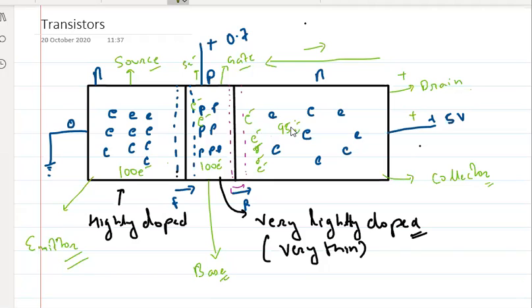And if this process happens rapidly, without any constraint, it will produce very high heat, and this whole junction can collapse. I hope all of you remember breakdown voltage. So that's why we have to maintain this reverse bias junction in such a way that the depletion region is thick as compared to this junction. In order to do so, we should have a lightly doped or moderately doped N side on this collector side.